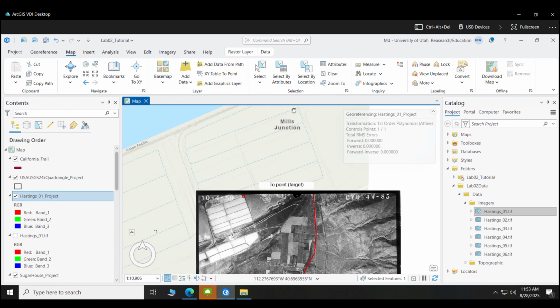So I'm doing another image for your help because first of all I will project this imagery and then I will georeference it in the same way. Actually, georeferencing these images is a bit more complicated because we do not have the grid lines showing up now on these images.